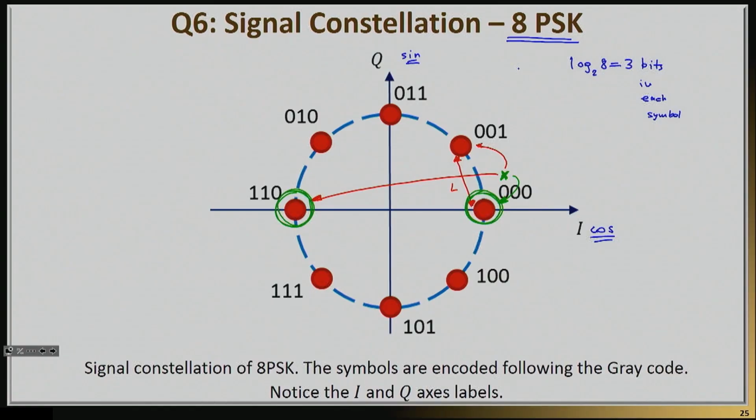You can immediately tell me that 8 PSK, yes, transmits 3 bits per symbol versus BPSK that transmits only 1, but it's far more likely to make an error because the distance between 2 neighbor symbols in the 8 PSK is much smaller than the distance between 2 neighbor symbols in BPSK. And that's why you will see standards, when there is high noise, actually reduce the data rates because they shift to a simpler modulation scheme, as I just described before.